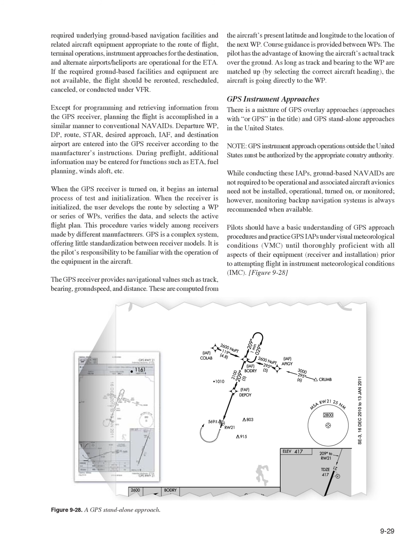Pilots should have a basic understanding of GPS approach procedures and practice GPS IAPs under visual meteorological conditions, VMC, until thoroughly proficient with all aspects of their equipment, receiver and installation, prior to attempting flight in instrument meteorological conditions, IMC. Figure 9-28.